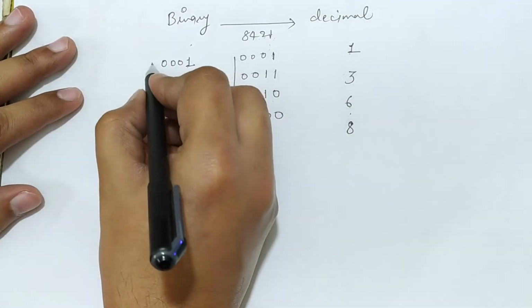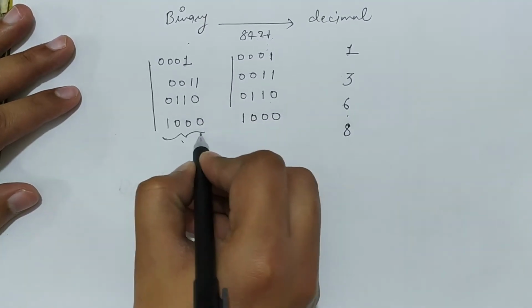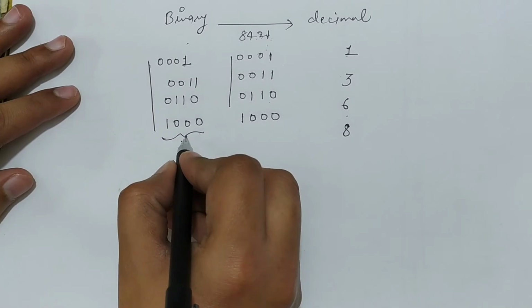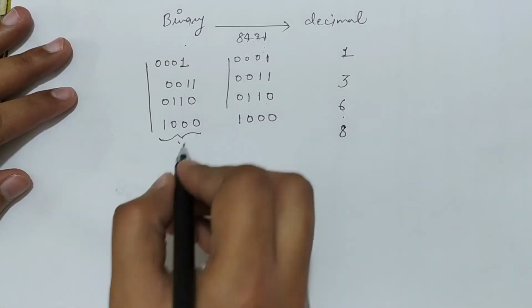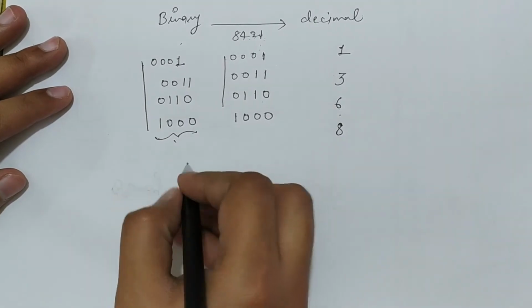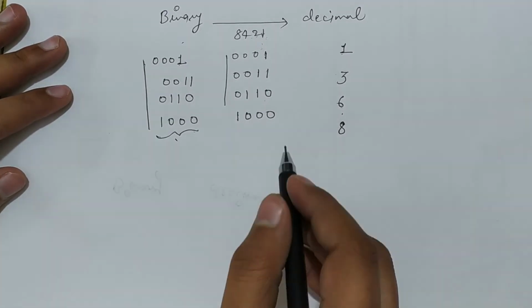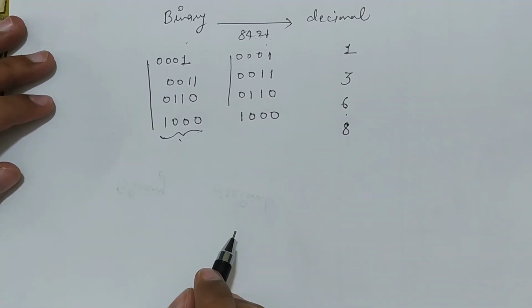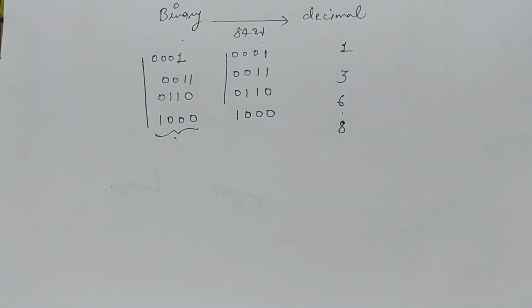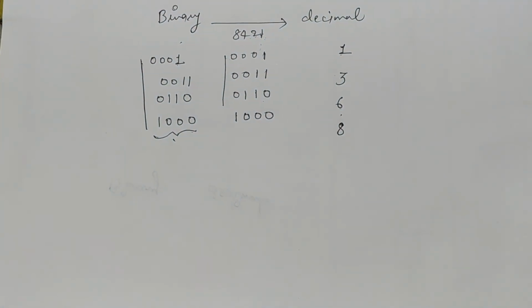So these 4 switches are the 4 bits, and I'm going to give these 4 bits of data using the DIP switches, and then this data will be fed into the 7441 IC, and then it will be given to the 7 segment display.